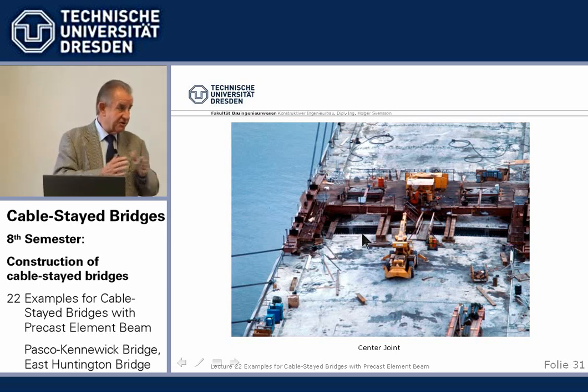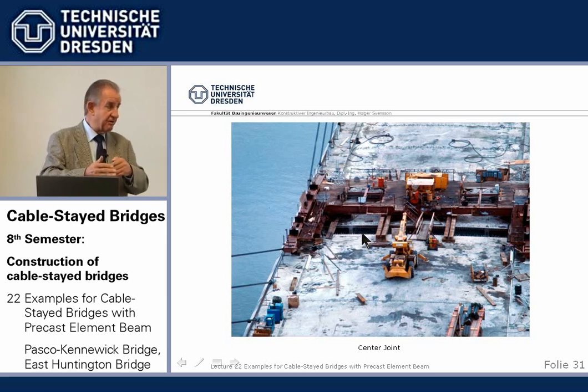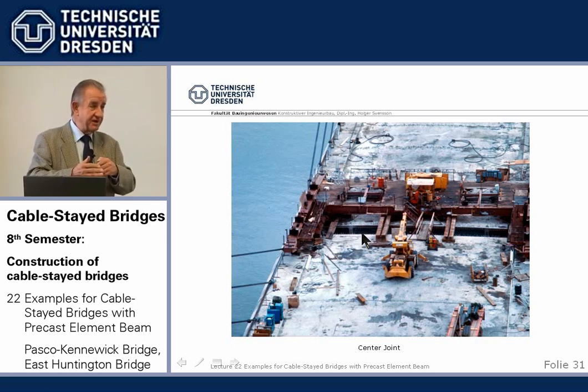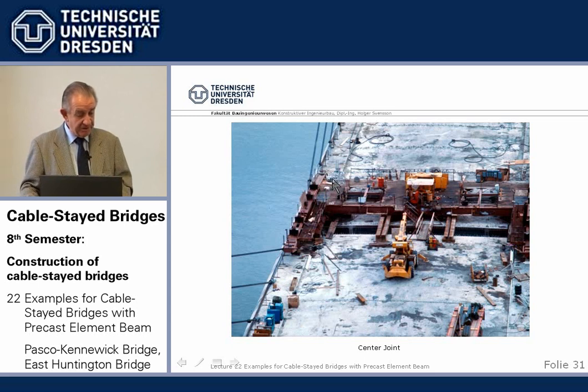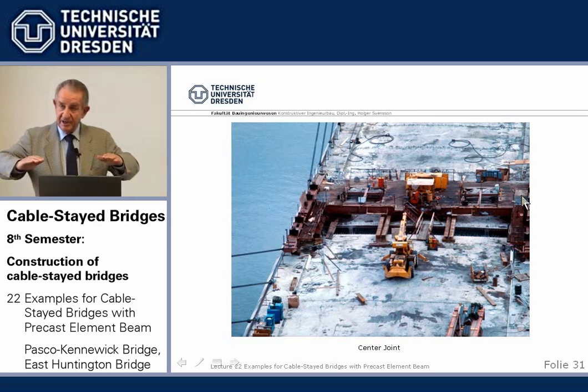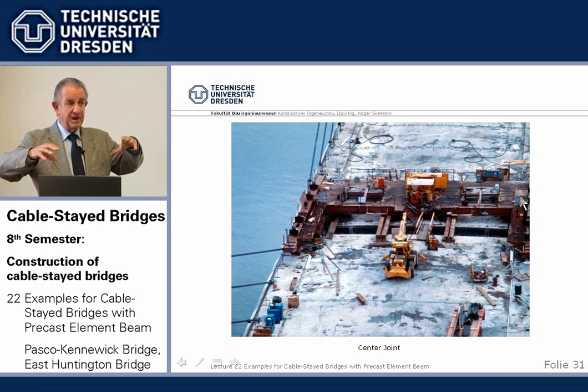You can do precast joints all the way, but you cannot do the very last one. You will not be able to fit precast elements in between to the millimeter. No way. So that has to be cast in place. And we had designed the traveler from the very beginning in such a way that we could stress the main part, the box, over the joint, because you need to use it as a splint, eine Schiene, like for a broken leg, to fix the joint, because it works.